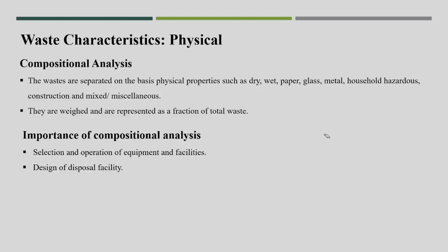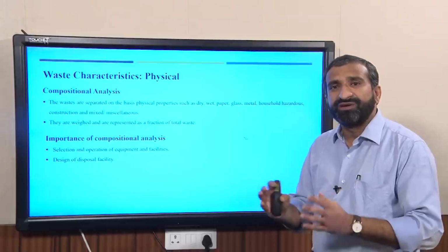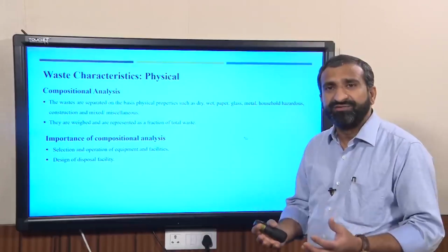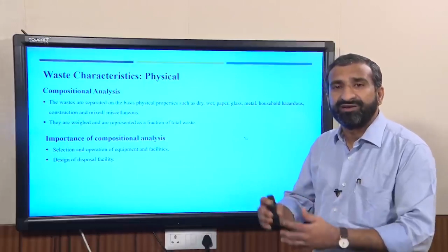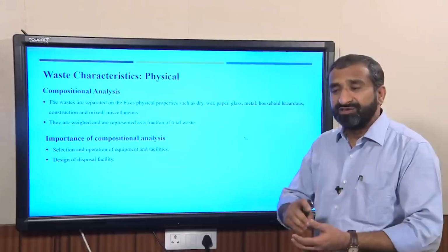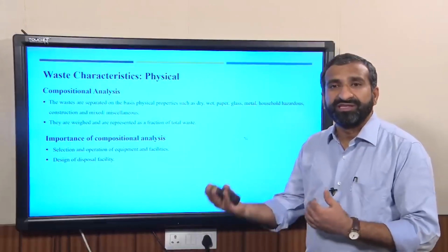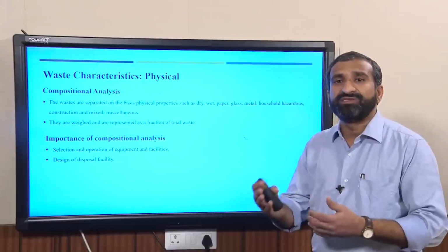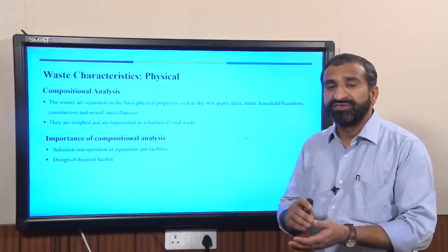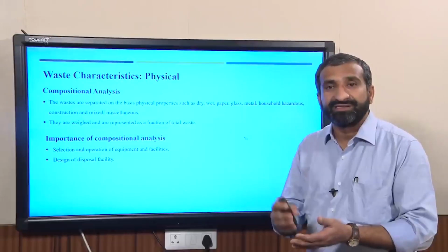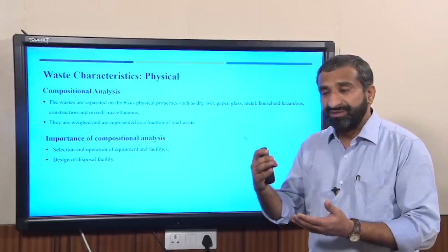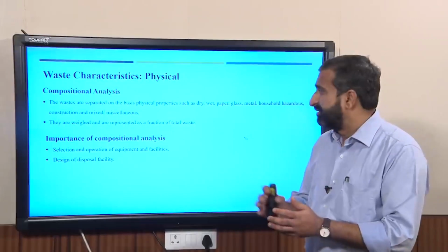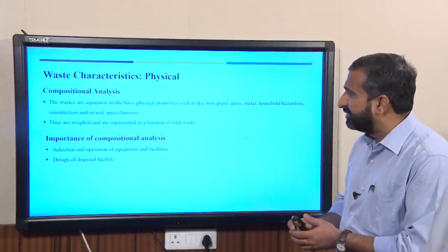Suppose without knowing the physical composition of the waste, like wet waste, it is very difficult to design a composting plant or biological treatment plant. And if you are planning an incineration facility and do not know how much combustible matter there is, like paper, plastic and rubber quantity, which are very important combustible materials required for the incineration facility.